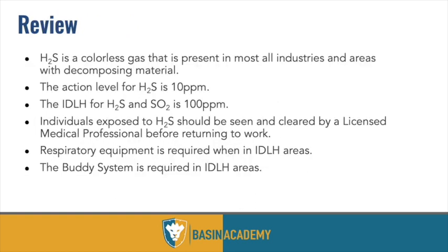So lastly, wrapping this up and summarizing, I try to keep it under an hour. We're just over, but we want to make sure that we understand that H2S is colorless, it's highly toxic, it's also flammable and heavier than air. It's formed when decomposing material happens, or really any time a sulfur element bonds with two hydrogen elements, then you're going to get H2S. The action level for H2S is 10 parts per million, meaning that that's the point where we need to muster up if we don't have the appropriate PPE.